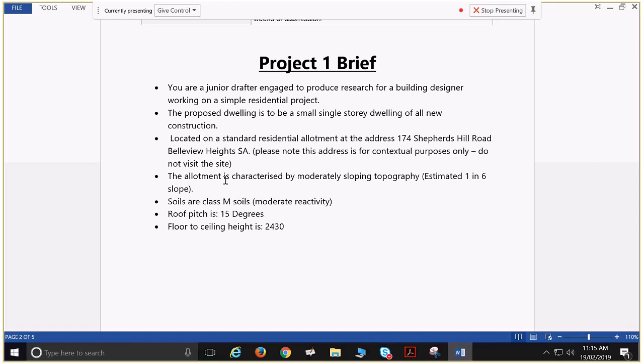If we're going to go with a lightweight flooring system that has very little load-bearing capacity, we're going to have a lightweight walling system and lightweight roofing system to go with that. We're probably going to go with a sheet roof, which is 10 kilograms per square metre, as opposed to a tile roof, which is 90 kilograms per square metre. I'm not expecting you to be experts in any of this, but what I am expecting you to do is gather those bits of information to be able to guide sensible decisions for clients, etc., who are far less informed, and pull that all together in a sensible way.